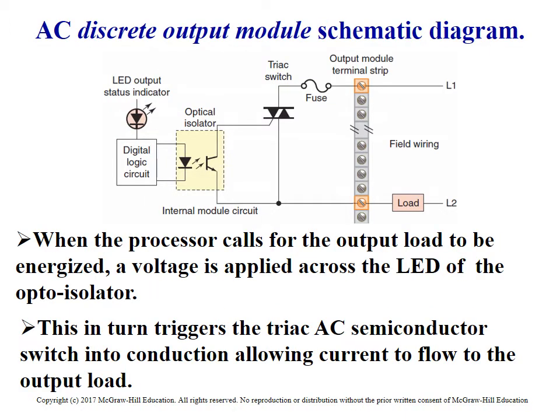And here's an illustration of that. Here they actually have a triac switch for that, and as you can see, they do fuse this particular one. Some of them are fused individually, some are not, so you just need to be aware of that.